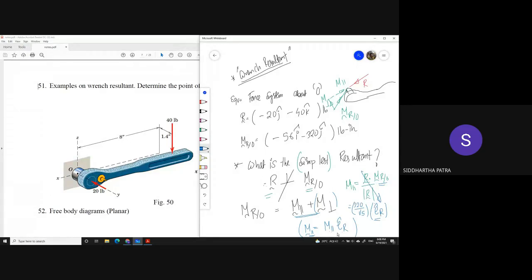So if I multiply the M parallel value with ER, I have the parallel component of the moment along with its Cartesian representation. All I have to do to get M perpendicular is a simple vector subtraction.